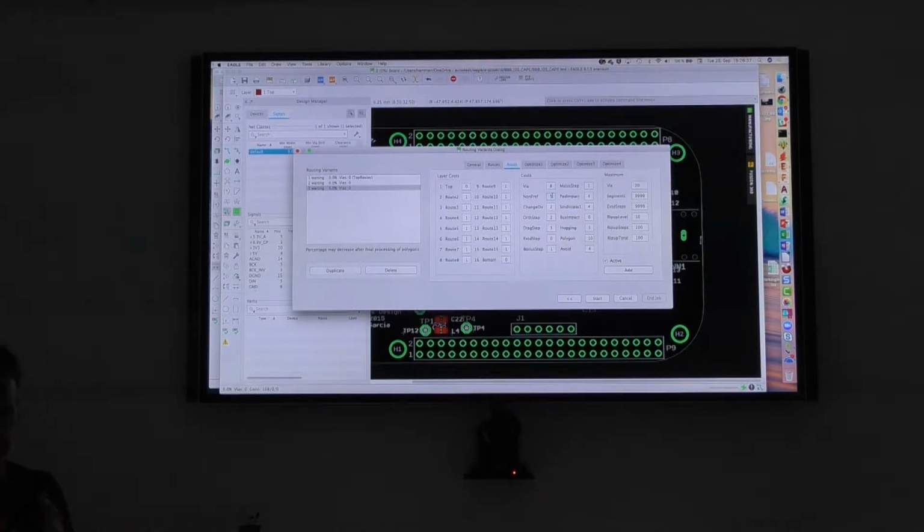So I get a cost for my path, and the router tries to take the cheapest one. Leave it as it is; that's the best way. There are some situations where you can change something. These are the 2 cases written in the manual, which you can read if you need. But I think the autorouter gets less and less important. We have the new tools, manual routing.